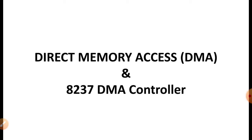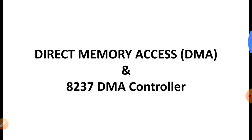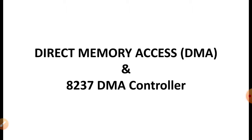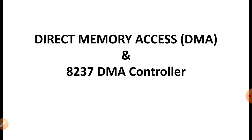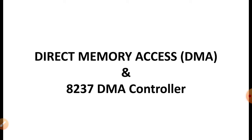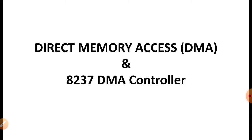So, if we have to transfer data from the peripheral to the memory, or from memory to the peripheral, or from one memory to another memory, then the normal process adopted is first to copy the data from the source to the processor, and then from the processor to the destination. The source and destination may be the memory, or the peripheral, or one may be peripheral and the other memory. So, it wastes too much time, because unnecessarily the data is being transferred from the source to the processor, and then from the processor to the destination place.